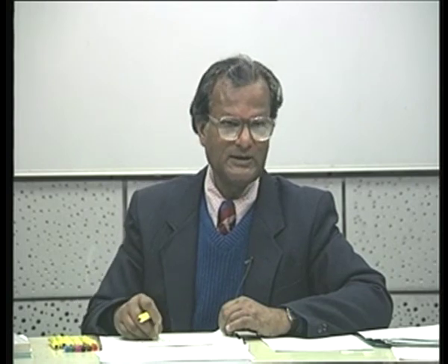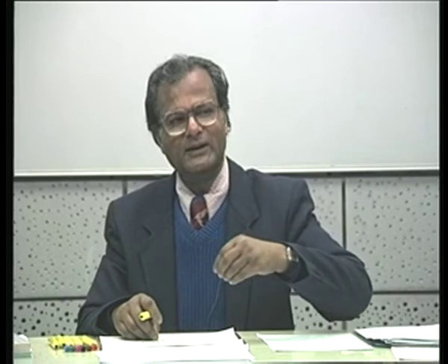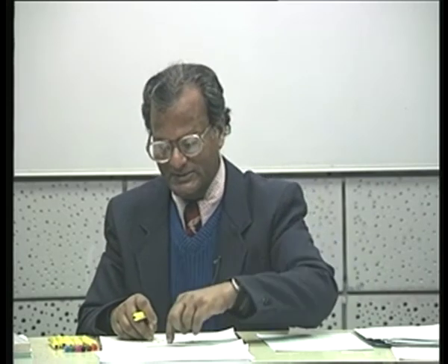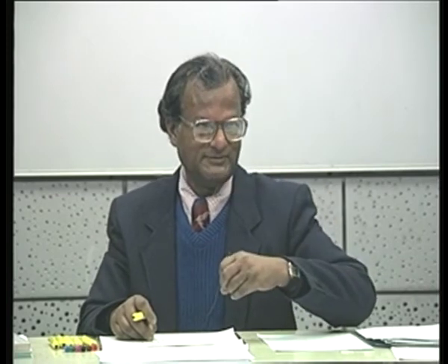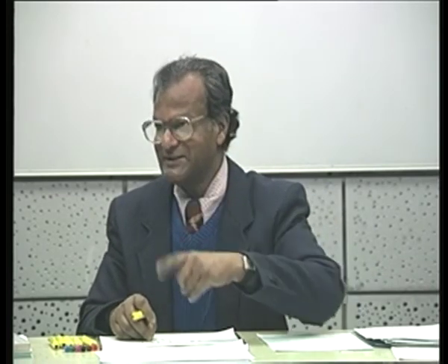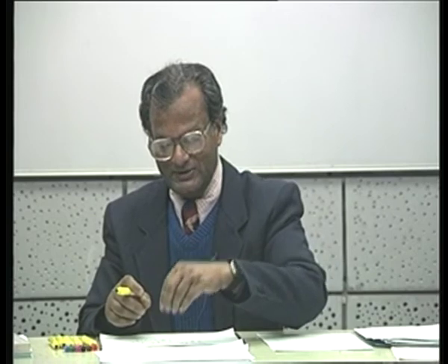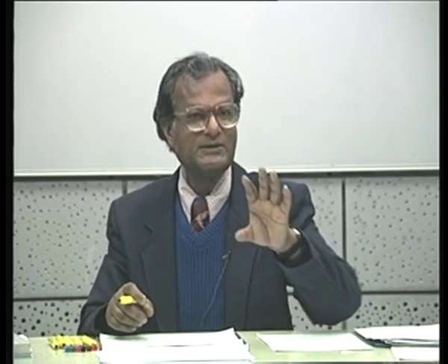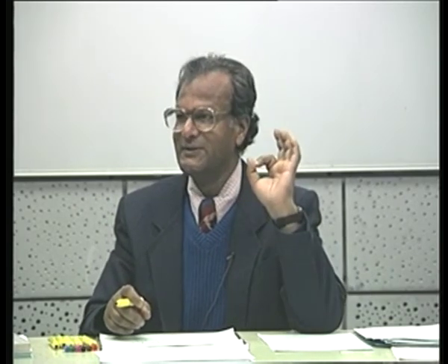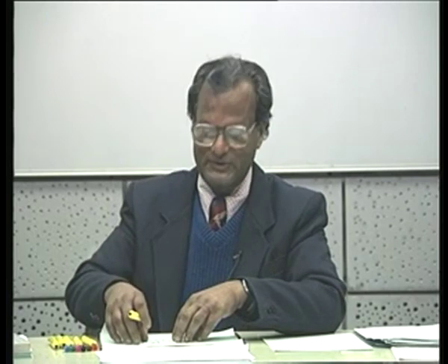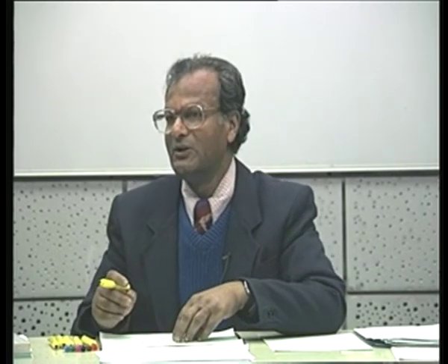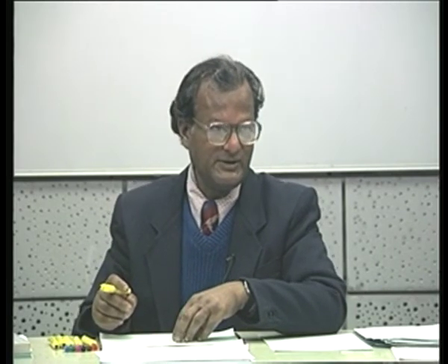The double tuned circuit is an example of coupling through magnetic field. The capacitive coupling is an example of coupling through electric field. If instead of a capacitor or inductive coupling there is a resistive coupling, it is a case of dissipative coupling. That is, energy is being transferred, but in the process there will be losses in the coupling resistance.